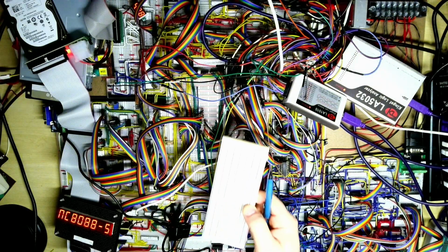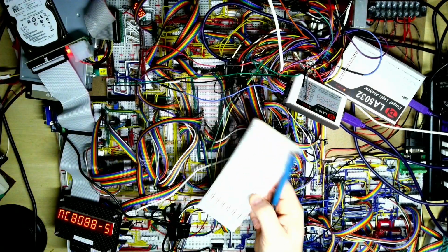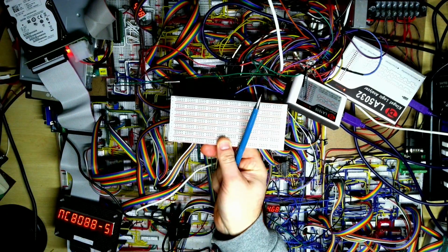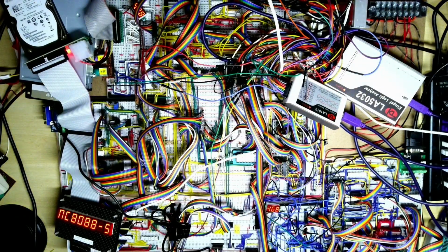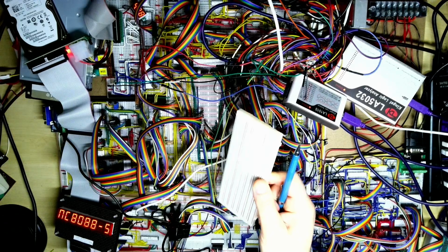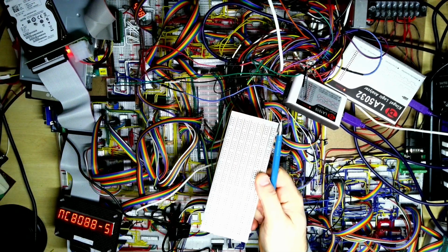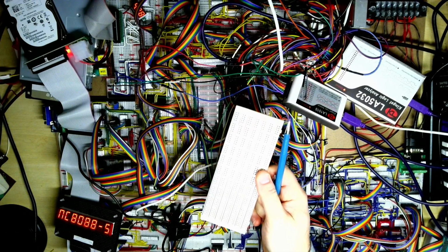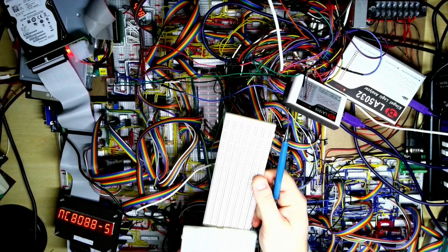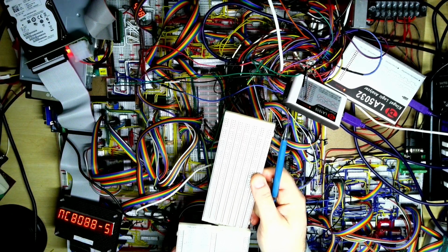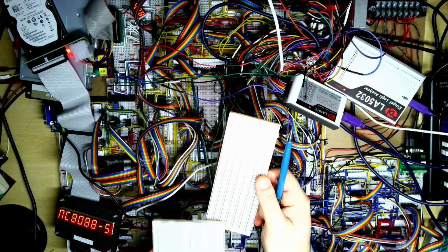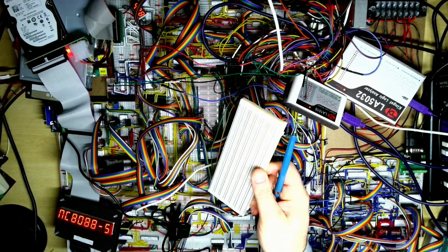We've also been using the power strips as bus connectors, so you'll see that the address bus and the data bus and some of the control bus have been using these as well. Now I was in two minds whether to use this. These have actually worked fairly well. However, there are a few problems with using them. In particular, the problem tends to be that the connectors are in twos, and so it makes it a bit easier for them to become pulled out.